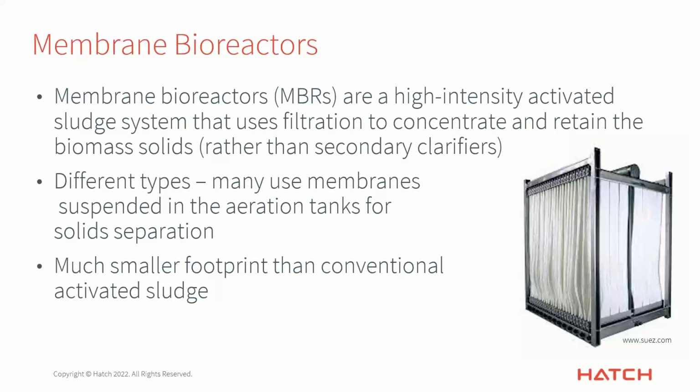They do have an extra cost, though, of course, in terms of the energy required to draw the permeate out of the system. And they do have some other operational considerations that you have to take into account. They have to be cleaned and backwashed, and you have to keep the solids off, and there's general maintenance to keep the membrane surface in good shape.